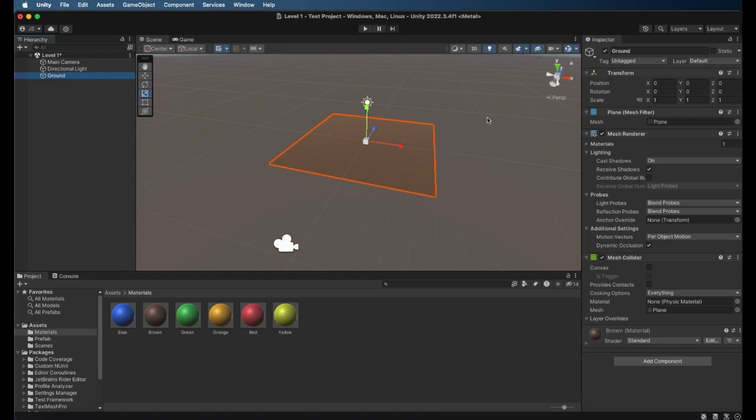And let's say I want this to be a little bit larger of a square here. So if I go ahead and grab that red and I start stretching this till it reaches the lines in my grid, you can see that this is 1.9971. If I want this to be precise, I can then change this value to 2 on the X. And I want to go and change this upward on the Z. So the Y is going up. I'm going to grab that blue handle and I'm going to stretch that as well so that I have a 2 by 2 square. You can see here that the Z is not quite 2, but I'm going to go ahead and type in the number 2 and hit enter.